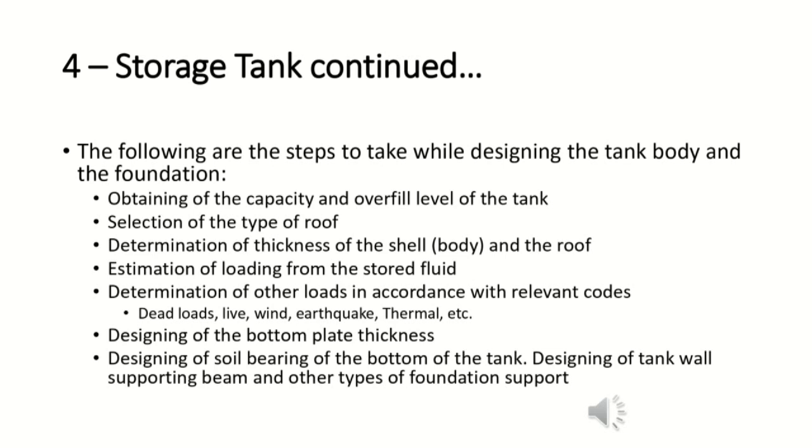3. Determination of thickness of the shell. The shell is the body and the roof. 4. Estimation of loading from the stored fluid. 5. Determination of other loads in accordance with relevant codes.